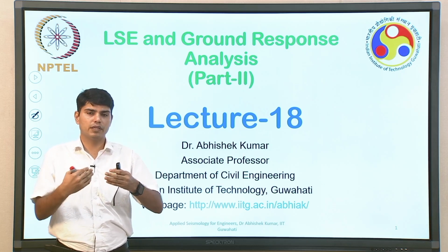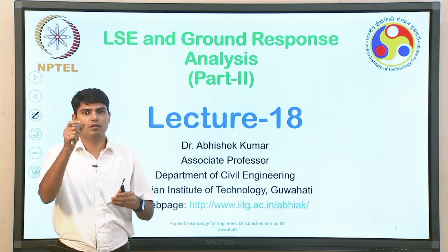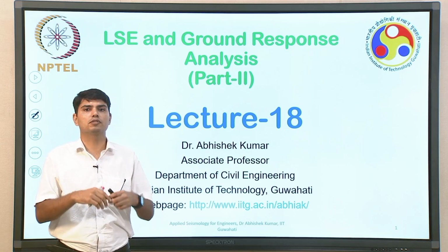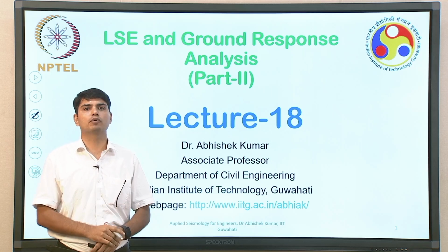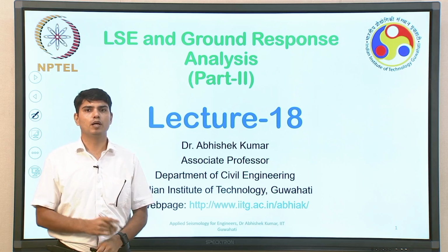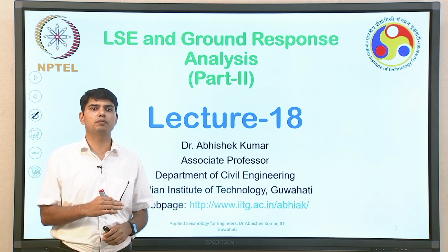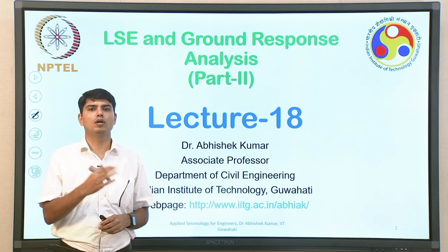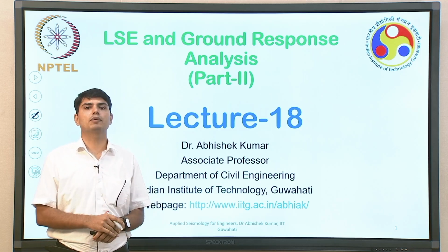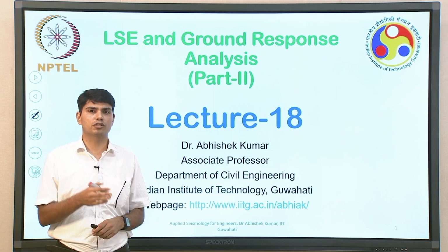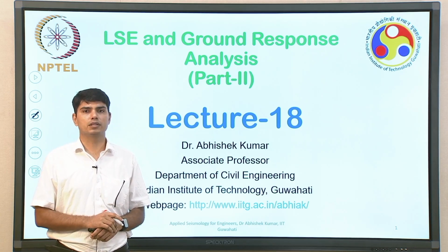motion. So, one is the input soil properties which one can determine based on in situ investigation as well as quantification of dynamic soil properties of soil. Input motion, if it is bedrock motion, you can directly use. If it is bedrock outcrop motion, you have to suitably modify that particular motion. Similarly, if it is outcrop motion, you have to transfer that motion to bedrock condition.